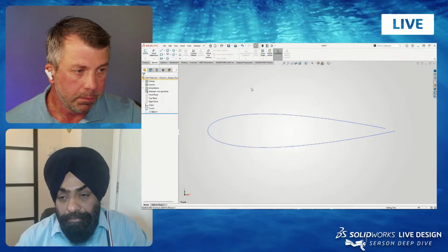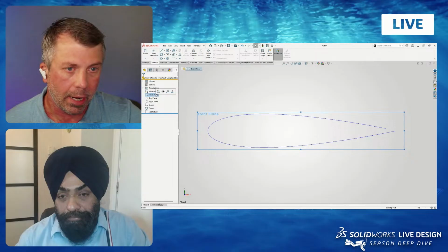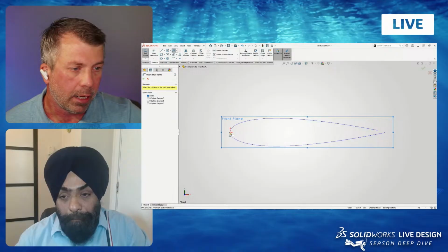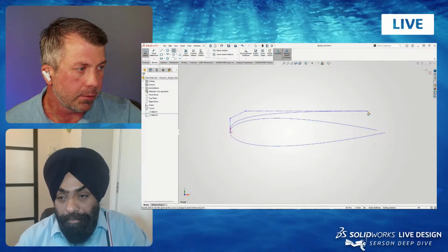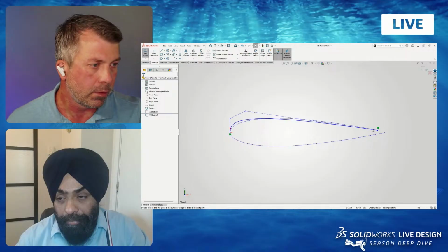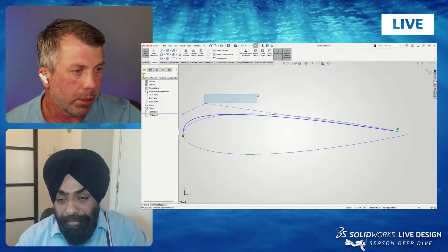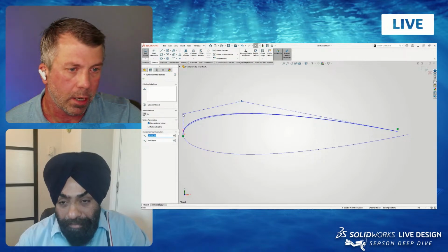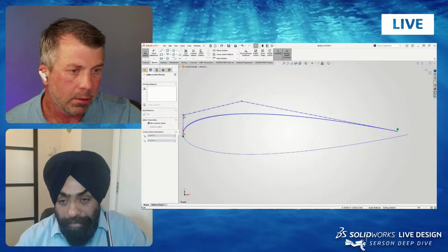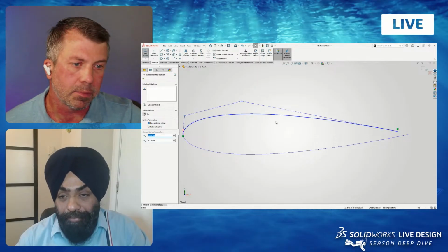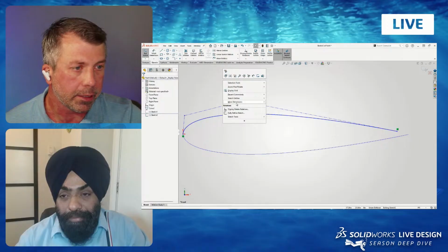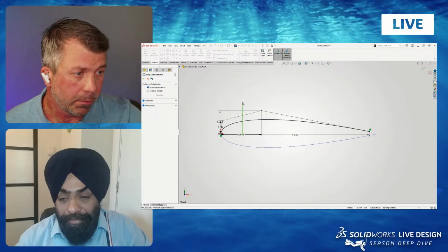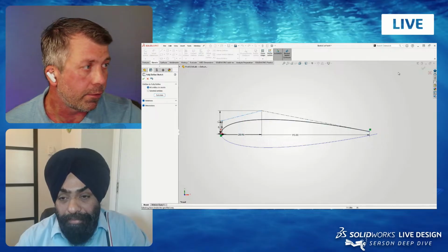The other way you could do it is simply coming in and creating style splines if you want to have a fully defined version of that. You're basically just going to trace this out, right? Again, don't try to build it and fly it, but you'll be able to get pretty much spot on to the curve. Style splines are a great way to derive splines because you can fully define these. So we can line that up and get a style spline. And again, if we want, right-click, I'll just cheat, say Fully Define, adds my dimensions in here. And now I have a fully defined top spline.